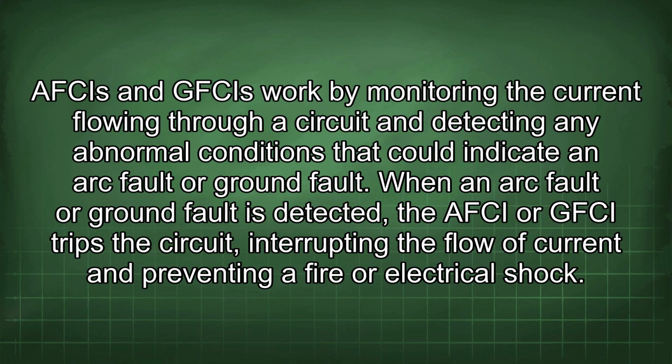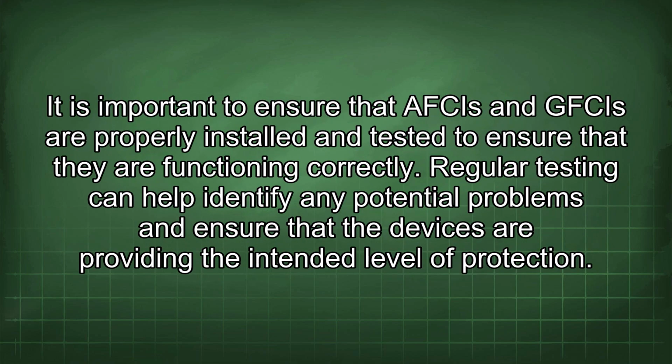AFCIs and GFCIs work by monitoring the current flowing through a circuit and detecting any abnormal conditions that could indicate an arc fault or ground fault. When an arc fault or ground fault is detected, the AFCI or GFCI trips the circuit, interrupting the flow of current and preventing a fire or electrical shock. It is important to ensure that AFCIs and GFCIs are properly installed and tested to ensure that they are functioning correctly. Regular testing can help identify any potential problems and ensure that the devices are providing the intended level of